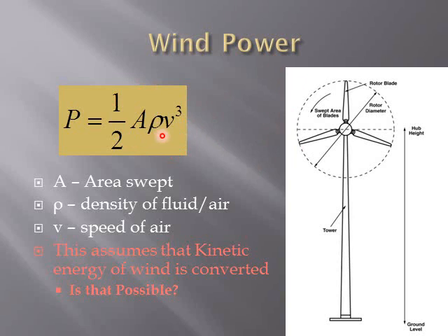So it's really this amount of energy before, and afterwards the same expression with the velocity afterwards. And keep in mind, if the air is slowing down, the air will actually become more dense, because you have more molecules coming through, and they'll pack up together, kind of like a traffic jam. As it slows down, the cars get closer together. So you'll have rho before and velocity before, and you subtract from that the density, or rho, afterwards, and the velocity afterwards, and that would be the total actual power.